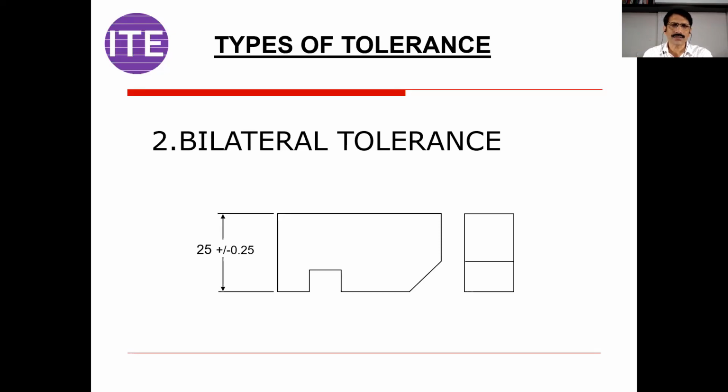There are various reasons. One reason is vibrations. Second reason could be spindle runout, machine inaccuracies. So you are going for the hole basis system. And when we say hole basis system, it means the hole is constant and you are changing the shaft.